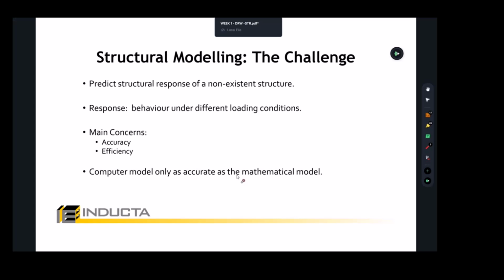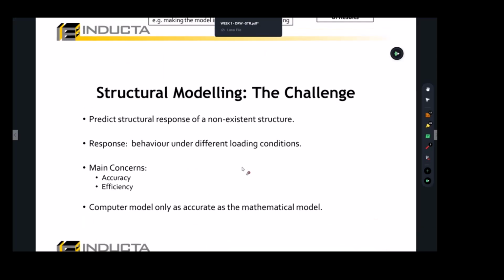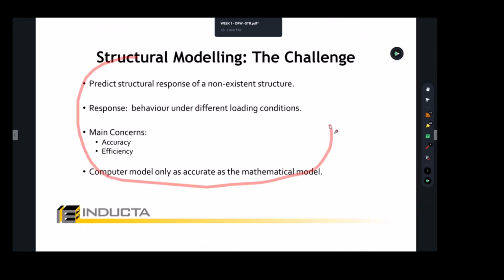And I do expect some of you will come up with very odd differences between the computer and your calculations, but that's what you need to investigate. Maybe you have told the software that the connection between the wall and the slabs is rigid, but it is not. Okay, so we will be sensing these kinds of differences as you go through the exercise.